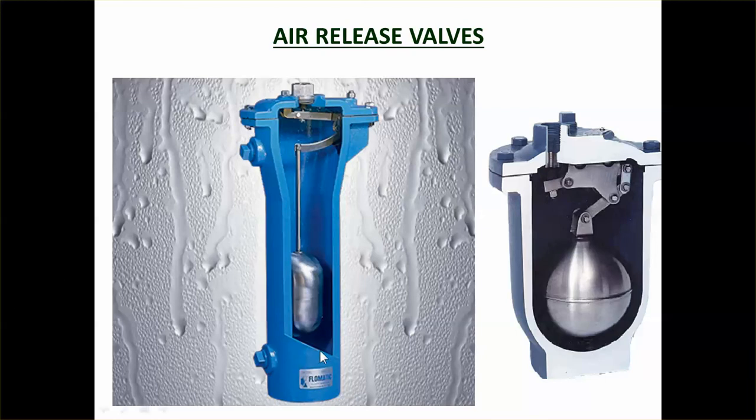And what you can see here is that if it's got water there, that float will lift up and close the valve. If there's no water there, it's just air, then that float is going to drop down because it's not floating on anything, and it opens up the valve and the air escapes. The water, when you open up that valve, is going to start going up again to fill the gap left by the air, and it will once again close the valve.